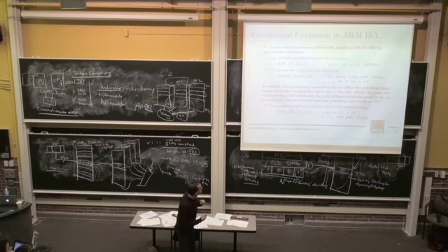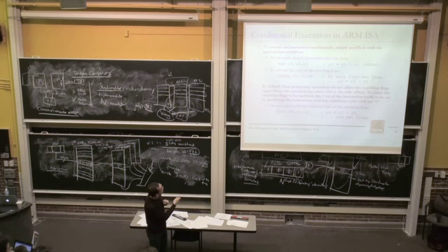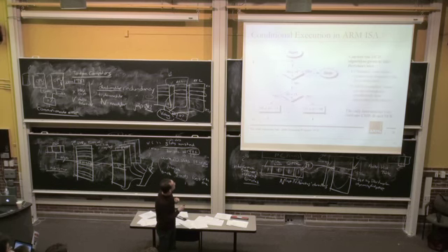And you can see how these bits can be set. For example, if you have an add instruction that you always want to execute, you do add always. If you have an add instruction that you want to execute only if the zero flag or zero condition code is set, then you use add equal, if you will. So what does this buy you?